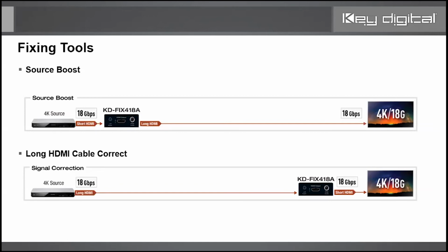Now, when is an example there? I would actually say at the top example, something like an AV receiver. A lot of surround receivers don't support long HDMI cables because they're not perhaps thinking about the systems that integrators are working with. Again, these systems are not point-to-point, one-to-one short HDMI cables. A lot of the time you have extenders, long HDMI, etc. So if it's an AV receiver, typically I would say put it at the front end, like we were showing on the front example.